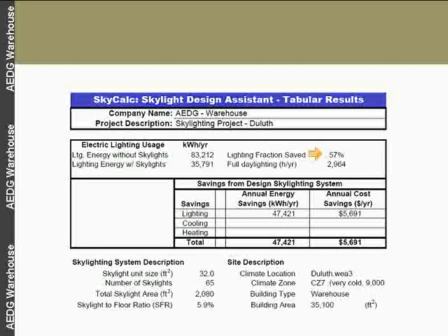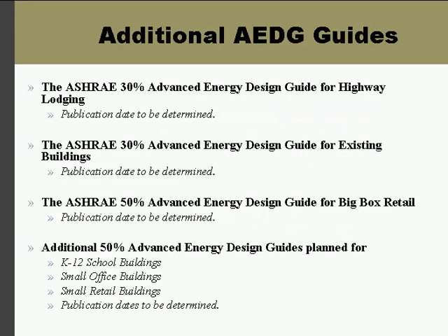And we were getting virtually no daylight savings in about 2 to 3 months of the year in the December, January, February time frame. So we did take out the skylights in Fairbanks. You could probably still use them, but you'd need to figure out some way to cover those skylights for those 3 months so you didn't have all that heat loss through the skylights.